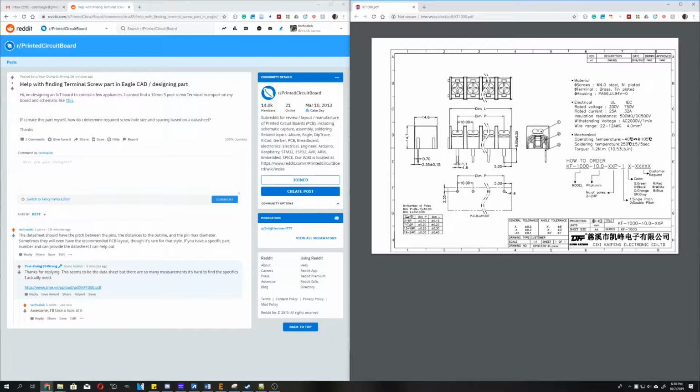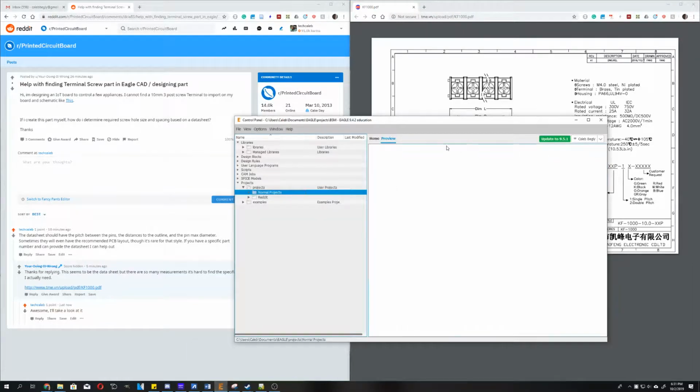We can actually look at our tolerance here. So because we're between 2 to 6 poles, we have a tolerance of about 150 microns on there. So we probably want to add in a little bit of tolerance for that. Finally, we have the width that we're looking at, and it looks like for all of these, that is 14.6. And you can also look at your pin offsets here, which we will look at more once we go to do the design. So let's show how you can do this in Eagle.